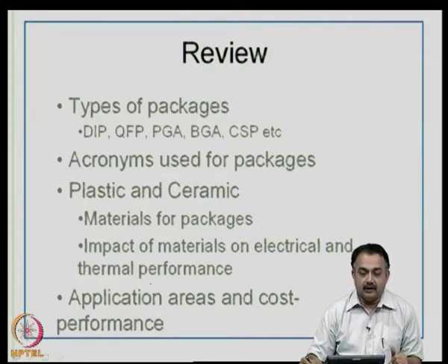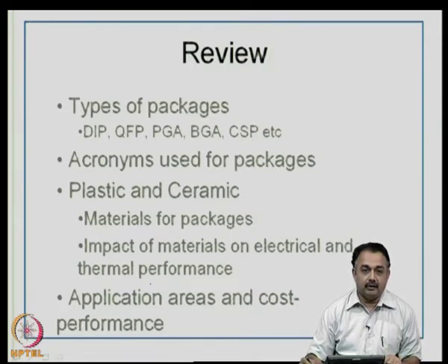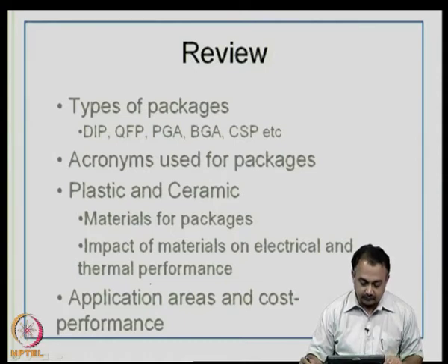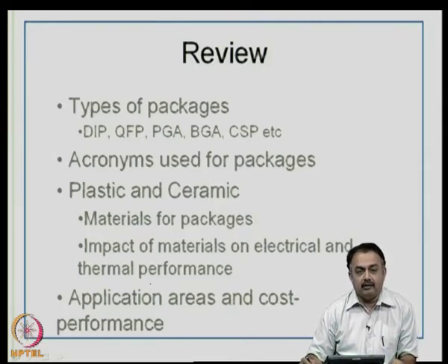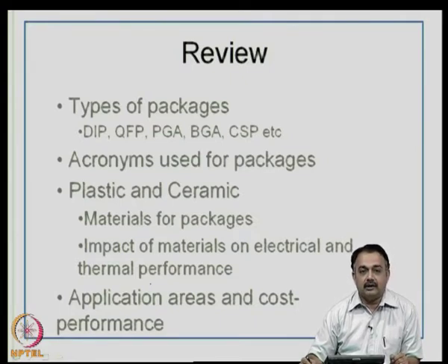live samples here, I have shown you each of these packages: DIP, dual inline package, QFP, quad flat pack, pin grid array, PGA, ball grid array, BGA, chip size package or chip scale package, etc. We have seen all of these packages, and we have spent some time on looking at the various acronyms used for these packages, because in day to day use you will come across various acronyms used, sometimes different acronyms for similar kind of packages.